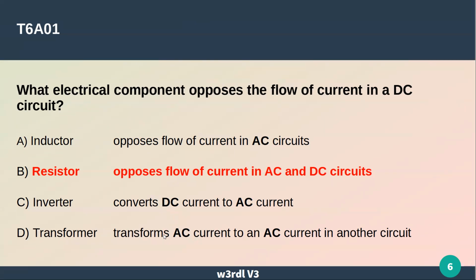Inverters are used to convert DC to AC, like for mobile use in your car, if you wanted to have a plug for an AC thing, you'd use an inverter. And transformers just transform current. There's no gain. Depending on the turns ratio, they can transform 120 volts into 12 volts at a higher current, but the power in is going to be equal to the power out. So there's no gain in a transformer.